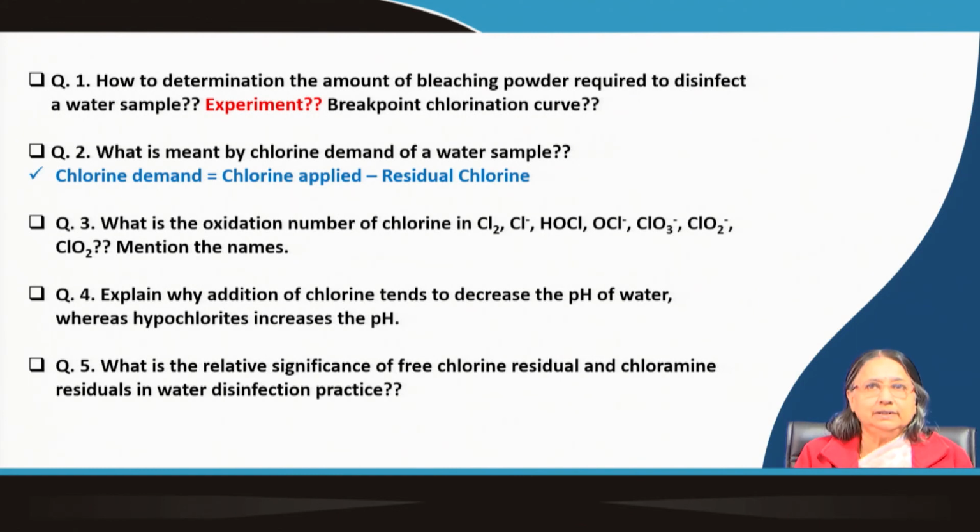I told you during transport the combined chlorine residual is very important, isn't it? That is the chloramine residual, and free chlorine residual, although it is a better disinfectant, is dissipated fast.